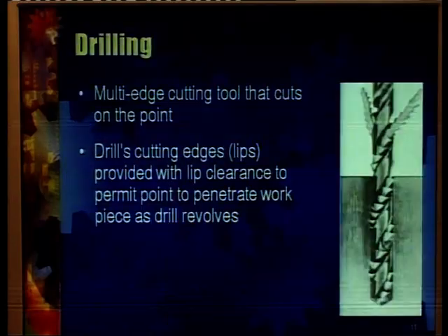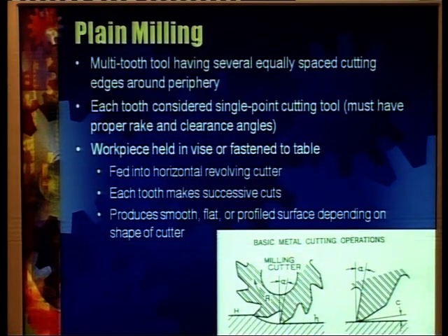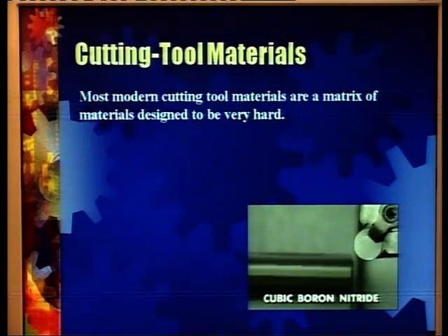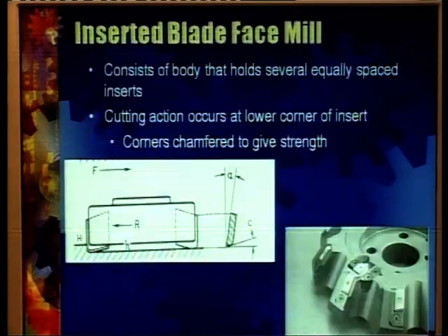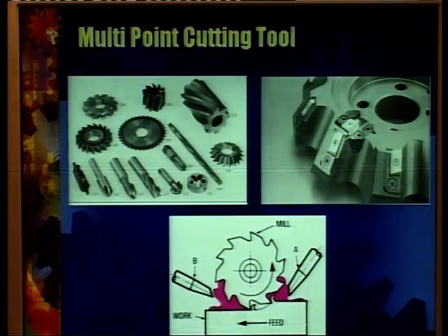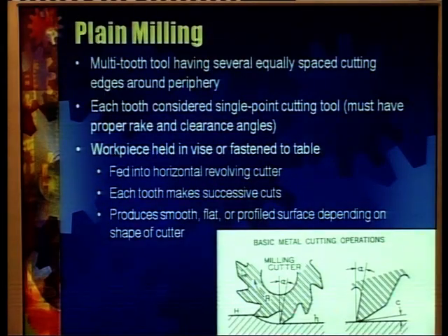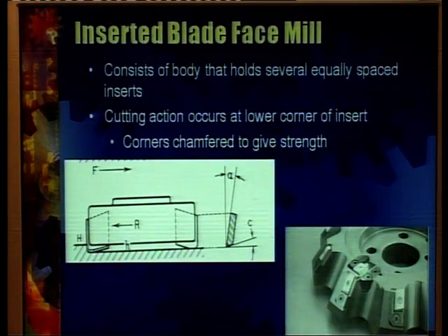What we mean by this paragraph is that in this type of machining, although we have a number of cutting edges placed on the periphery of the cutting tool, while studying the machining process we can still safely assume each and every cutting edge of this cutting tool to be just like a single point cutting tool. So, the basic unit of any cutting tool is basically a single point cutting tool. This I have already explained.